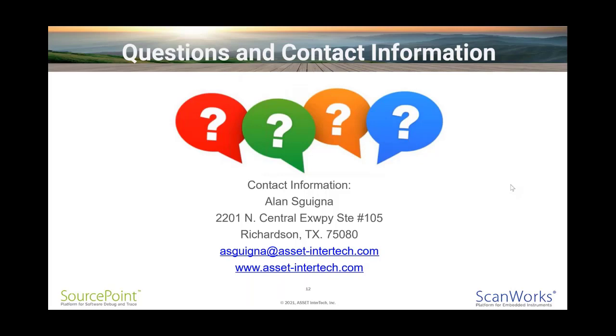What you saw today is primarily run control. There are some nominal trace features available on AMD, but nothing to the extent of architectural event trace, for example, or Intel processor trace. Also, Intel has the direct connect interface, or DCI capability, sometimes called DBC debug class, that allows you to go in over a specialty debugging USB cable and do debug that way, as opposed to going in from an open chassis approach via the HDT plus header.